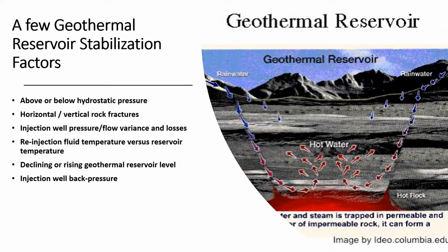However, when reinjection fluid temperatures are cooler than reservoir temperature, as is often the case, the mobility ratio reduces to the ratio of viscosities of the cooler injection fluid and warmer reservoir fluid, in turn reducing injection well flow in most cases with a resultant increase in pressure. This circumstance must be recognized and effectively managed by the system operator.